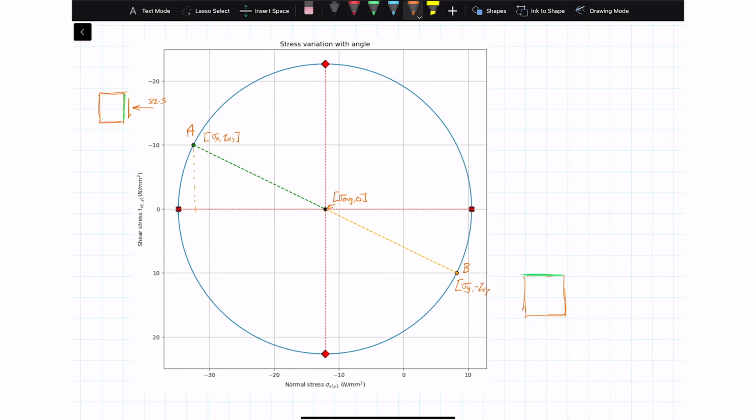All right, and of course that's just the stresses on the face that we've already pointed out, and so that was going to be a tensile stress. So it was a positive normal stress, which made it a tensile stress. So that's 8.2. And what did we have? We had a positive shear stress, so that's going to be a stress in this direction. Because you can imagine that is a positive y face, but to rotate around to that face, our set of axes would also be rotated. So our set of axes would now be the x1 axis after you've rotated by 90 degrees, that would be the x1 and that would be the y1, and so that arrow would be a positive shear stress because it is acting on a positive face in a positive y1 direction.